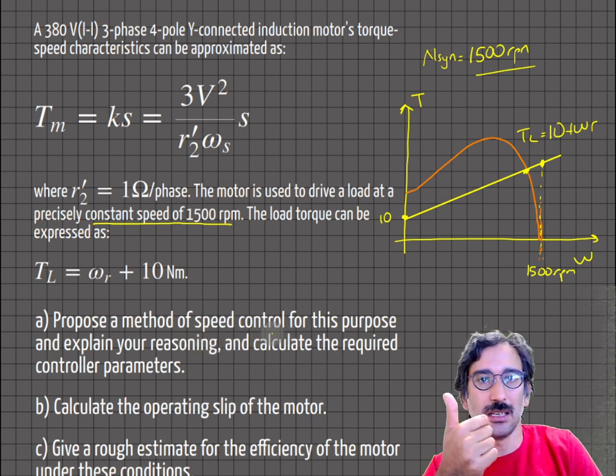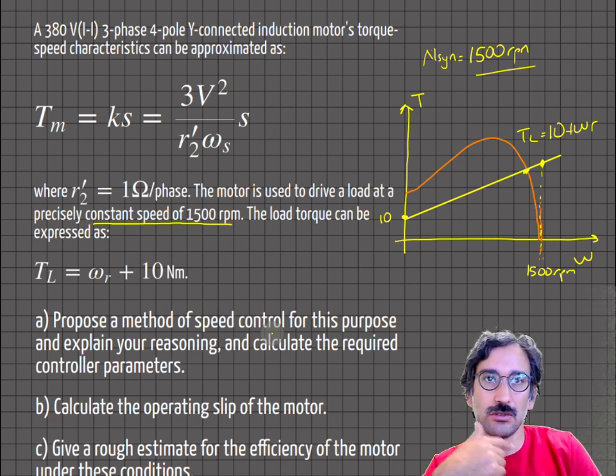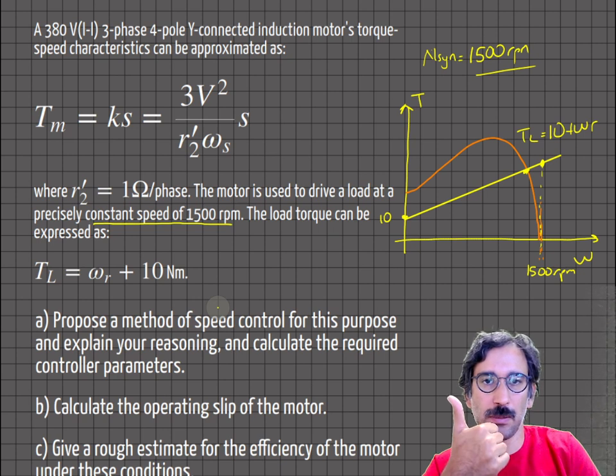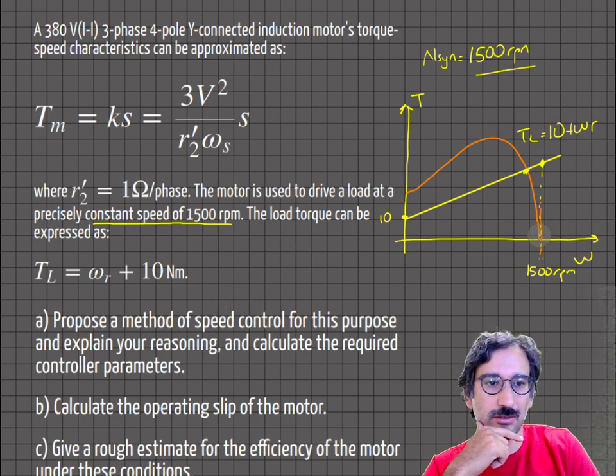control method. I mean, just to remind you, we can change the magnitude of voltage, connect some external rotor resistance, we can play with those parameters, but both with the voltage variation at 50 Hz or external rotor resistance variation, it's not possible to move that synchronous point.